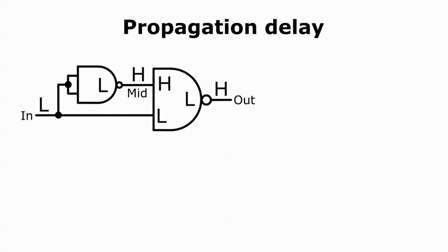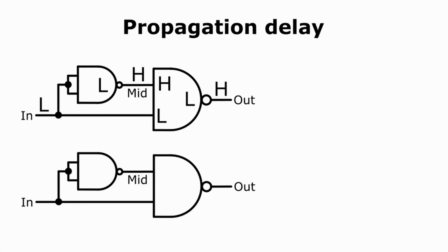What happens when the main input goes from low to high? To keep things clear, I'll redraw the whole circuit again and work through the consequences of the high input. The first NAND will invert this output so the voltage at mid will be low. The two inputs of the second gate will be low and high. The internal AND function will generate a low, which after inversion will make the main output high. We can conclude that the output from this circuit will always be high.